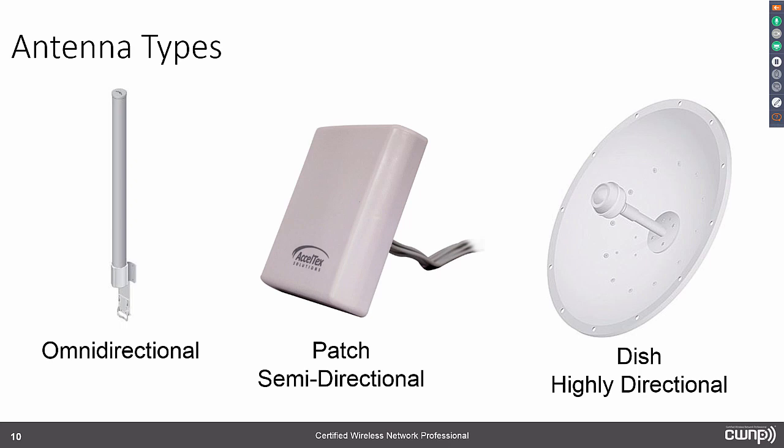It is important to note at this point that when I say high gain for transmission and reception, an antenna's gain is not unidirectional, it is bidirectional. The same gain that allows it to push the RF energy further in a particular direction also allows it to receive signals that might be too weak for a low gain antenna. That high gain antenna, if the signal's aimed at it appropriately, can receive it and process it more effectively.